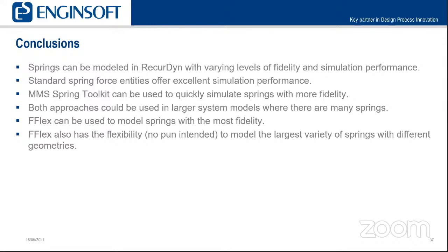Okay, great. And here's another question. How did you achieve smooth contact on the CAM or tappet interface? Yeah, the contact was a 2D contact. And that was just for the highest simulation performance. So the 2D contact, meaning that you're representing the curvature of the cam with just a single profile curve, and then the top of the tappet just had like a straight line. And so we're modeling contact between those two 2D elements.